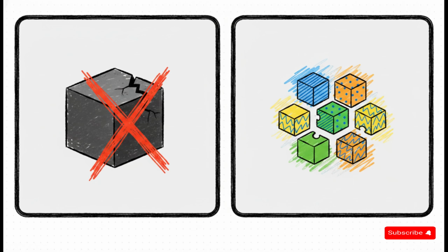The modern solution is disaggregation, better known as chiplets. Instead of building one giant chip, you build a team of specialists. You break the system apart into smaller, highly specialized dies. Smaller dies automatically mean you get a higher manufacturing yield. But even better, you can mix and match your technology nodes. You can use a super expensive, cutting-edge 3-nanometer node for your core logic, but then use an older, much cheaper node for basic I/O functions and stitch them all together in one seamless package.